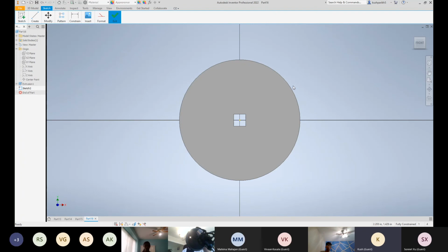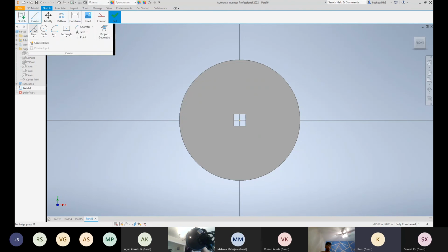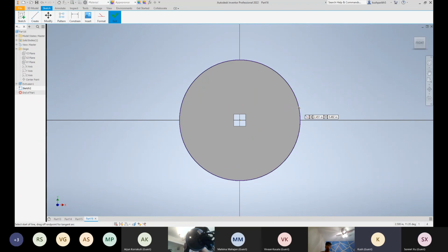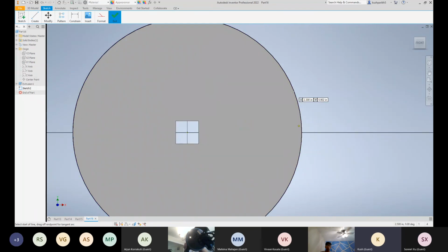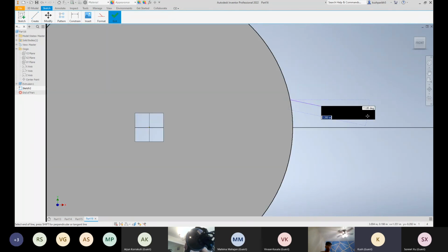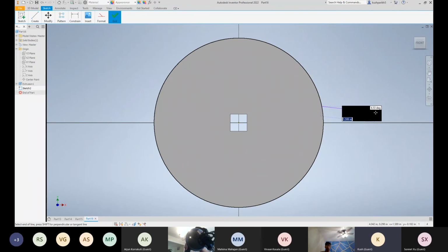This is something we covered yesterday. We'll be using a lot of things that we used over the past 3 days, so it's good review as well. I'll start off by clicking the line tool, and I'll make sure to press somewhere on the edge of the circle. So press like that, and then let's just go out a little bit like this. Just left click your mouse.